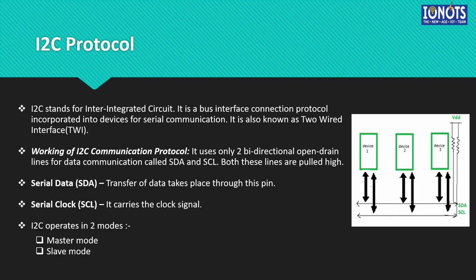There is another concept which is prevalent in I2C, that is clock stretching. I'll just briefly touch upon it. We won't go much into detail of it. The clock is stretched when the slave device is not ready to accept more data by holding the SCL line low, hence disabling the master to raise the clock line. Master will not be able to raise the clock line because the wires are wired-AND, and it waits until the slave releases the SCL line to show its readiness for the transfer of the next bit.